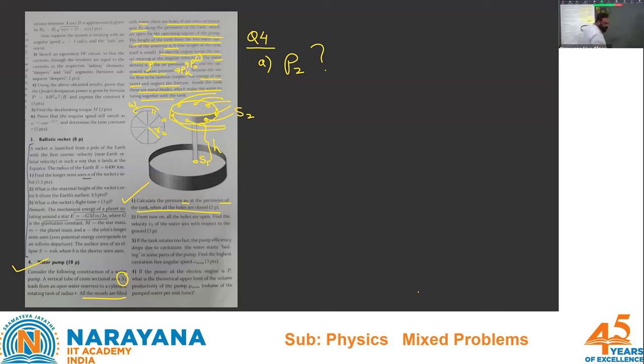So all the holes are closed. So by virtue of omega also, that centrifugal thrust is developed, but motion is not there. So on the surface I can write pressure as P naught. Even if this guy is rotating with omega, the pressure that I want to write is P2 is P naught minus rho gh term.